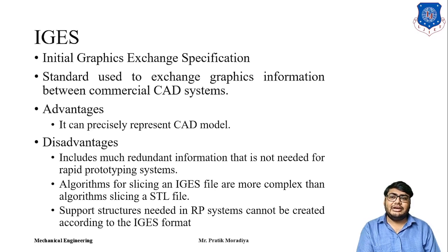So they decided to come up with a common file format, and they came up with this Initial Graphics Exchange Specification. Now that is the standard used for graphic information between commercial CAD software. What are the advantages of this IGES? It is a very precise representation of a CAD model. So IGES can accurately represent any CAD model.